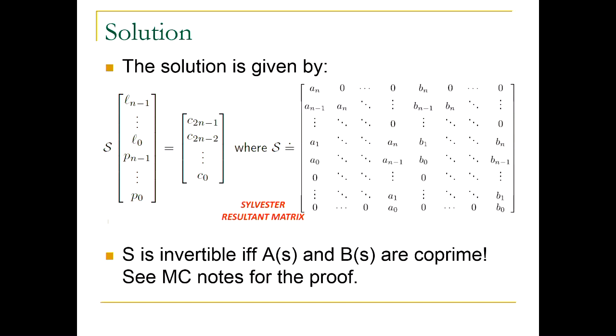Later on, in advanced control, if you do this subject, I will connect pole zero cancellation to the fundamental properties of controllability and observability. You will see in that subject that if there is pole zero cancellation, then either the system is not controllable or not observable, or both. These are fundamental properties, controllability and observability, and they are fundamental for pole placement in particular.